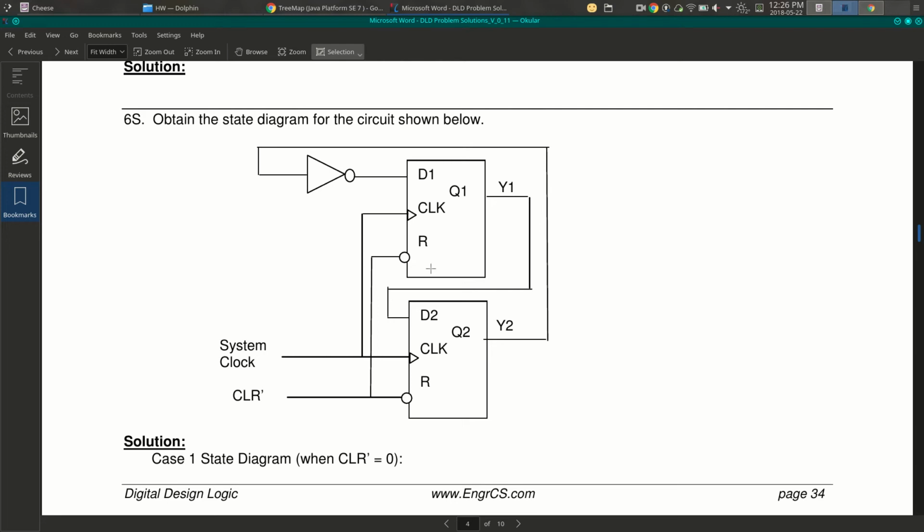So that former case, that's called an asynchronous clear. Means as soon as I set that clear line, the flip-flop gets cleared. Doesn't matter what the clock's doing. With a synchronous clear input, I would assert the clear line, and then when the clock ticks, it clears the flip-flop. And you can buy devices of both types. You can buy them with an asynchronous clear and a synchronous preset. There's different versions for different applications.